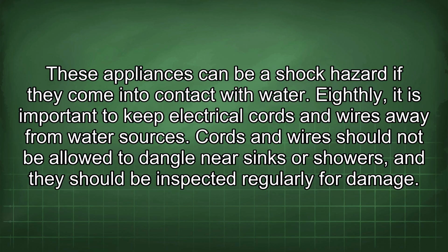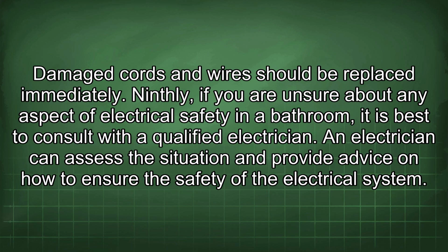Eighthly, it is important to keep electrical cords and wires away from water sources. Cords and wires should not be allowed to dangle near sinks or showers, and they should be inspected regularly for damage. Damaged cords and wires should be replaced immediately. Ninthly, if you are unsure about any aspect of electrical safety in a bathroom, it is best to consult with a qualified electrician. An electrician can assess the situation and provide advice on how to ensure the safety of the electrical system.